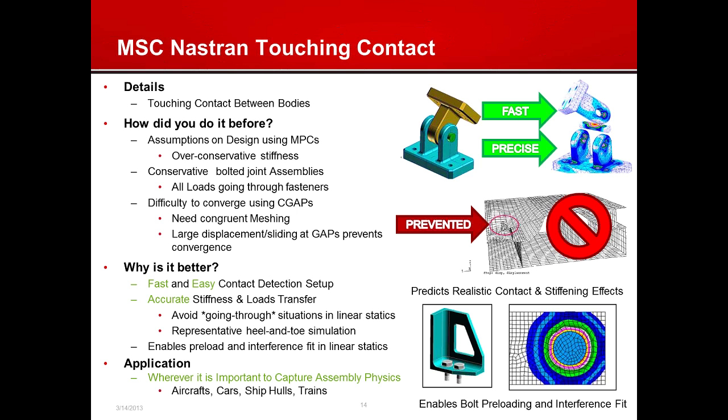Obviously, you have to maintain relatively small displacement, deformation, and small strain in your results for the results to be credible. But if you get started with linear static solutions and you have decent results that satisfy those criteria, then obviously you're able to get much more realistic physics into your model where things will settle together and the load flow may be completely affected.